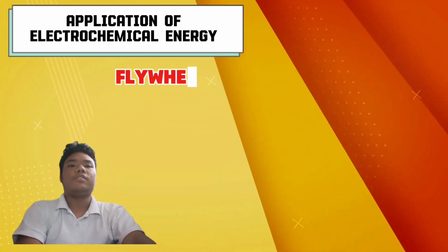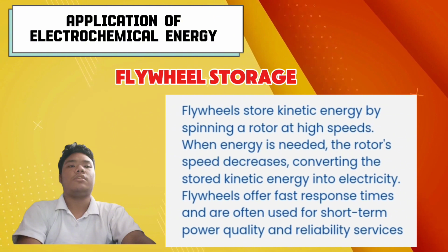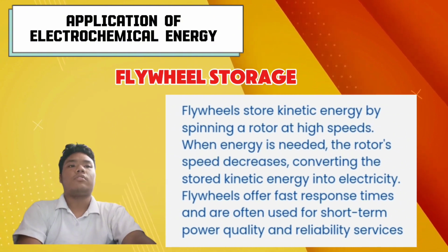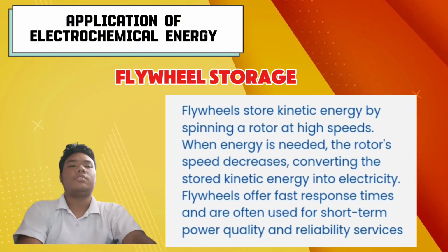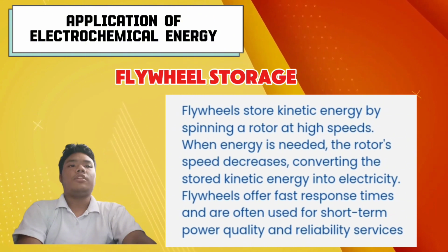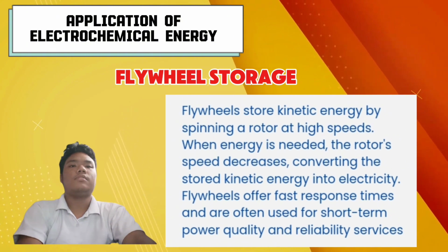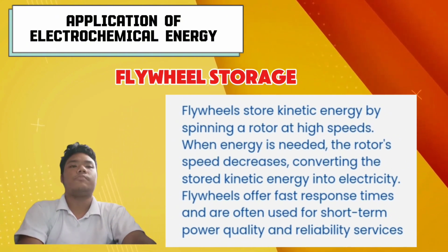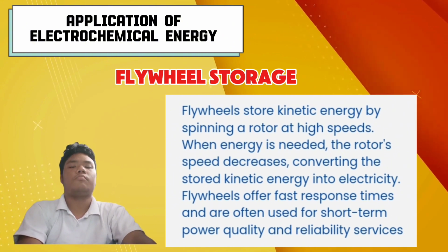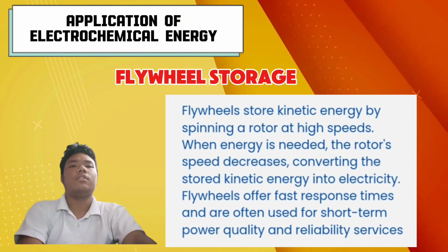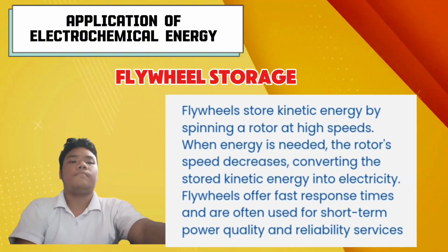Second, flywheel storage. Flywheel storage stores kinetic energy by spinning a rotor at high speeds. When energy is needed, the rotor's speed decreases, converting the stored kinetic energy into electricity. Flywheels offer fast response time and are often used for short-term power quality and reliability services.